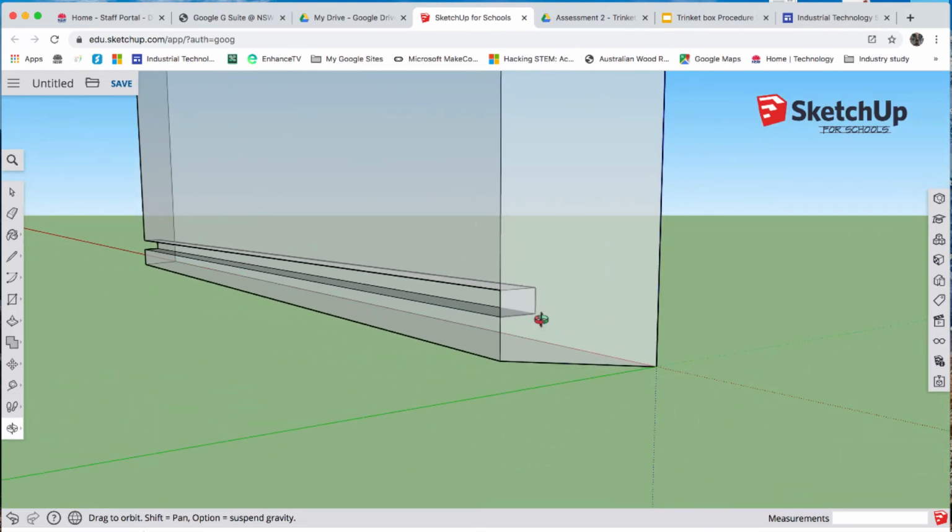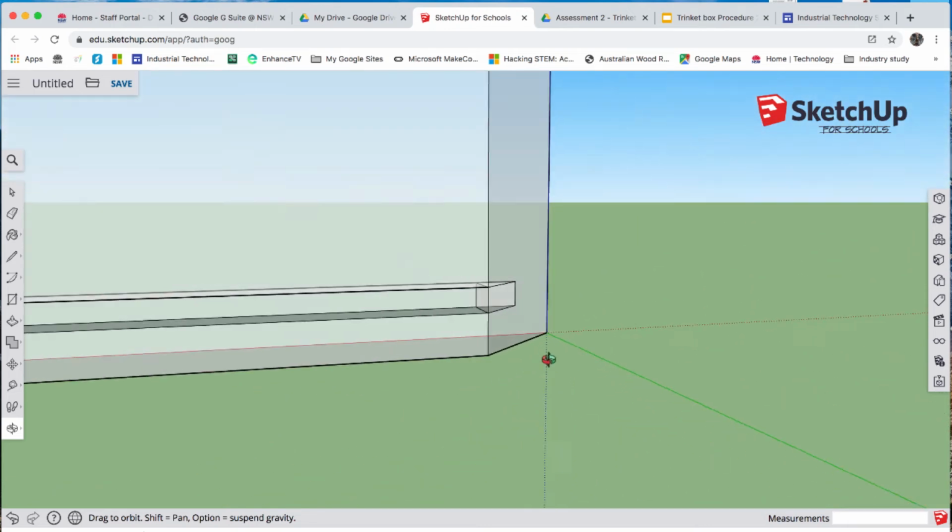Okay, we'll get in nice and close. L for line. So here we'll go, yep, on face, escape, left click again, on face, join these two together, join that together, join that together, and then we'll orbit around again. So shortcut O, orbit around,